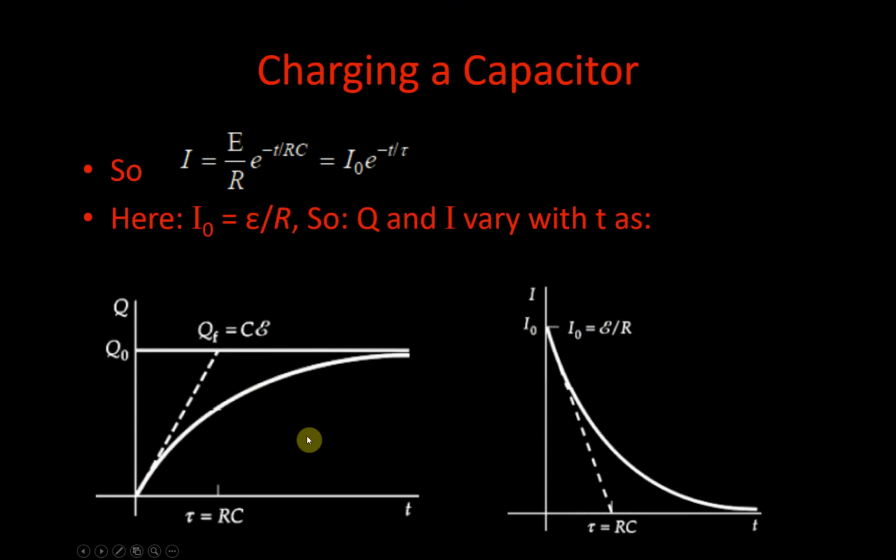So what people usually do is put these two graphs together, but here I0 is identical to the discharging case. This is the charging case. The discharging case, remember, Q went down, so I went down. In this case, the current starts off high and then diminishes. The current slowly falls off with time in this exponential fashion.